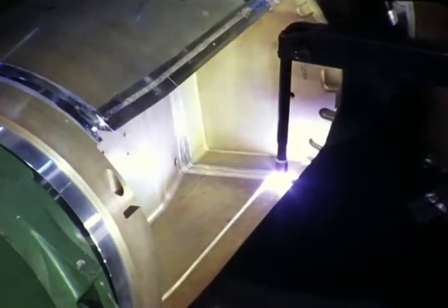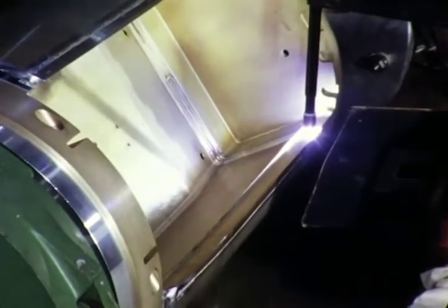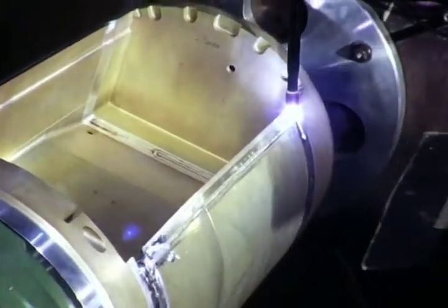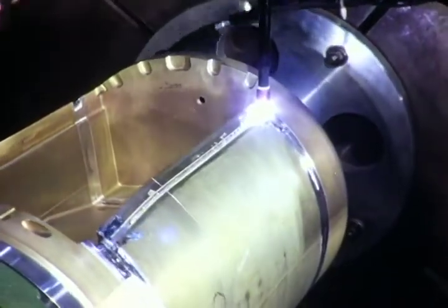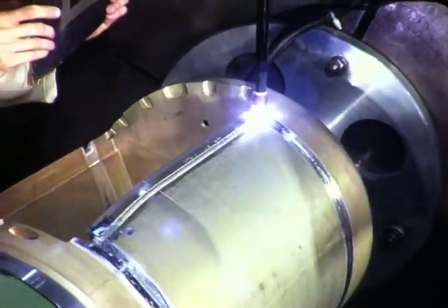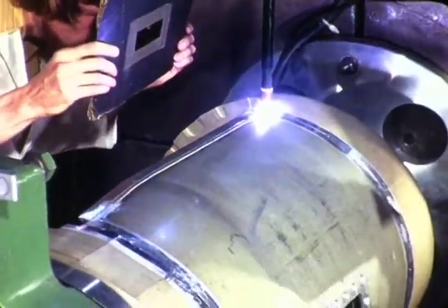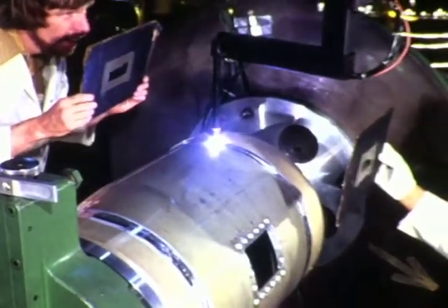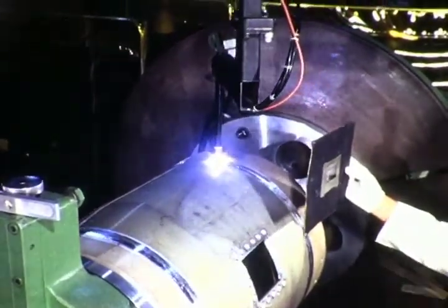All welding parameters are normally maintained constant in long, continuous areas, and the computer is reading the digital output of the drive encoder, in this case the turntable shaft position. The next table position flag triggers the computer to read the next data line from its memory. The next line at this joint contains a data word to command the torch rotation motor to operate. The torch arm assembly must be repositioned 180 degrees to permit re-entry into the cavity area from the opposite side.